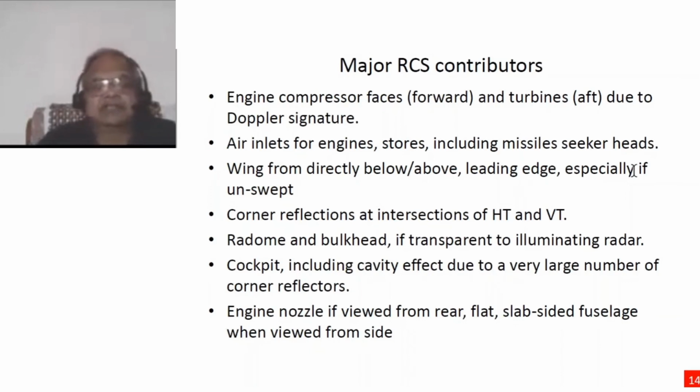Another thing is, because these are rotating devices, there is also a Doppler shift in the radar which comes in, so that will help the radar detecting systems to be able to identify systems. Air inlets for engines and stores, meaning whether they are bombs or missiles, which normally are carried under the combat aircraft, and missiles themselves have seeker heads. So all these are possible reflectors.